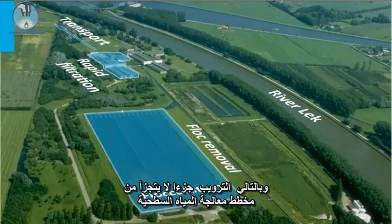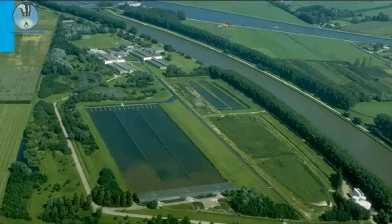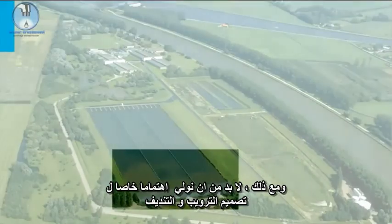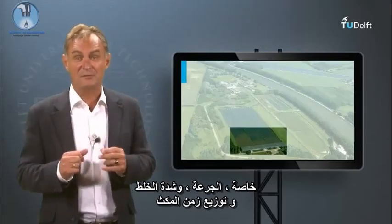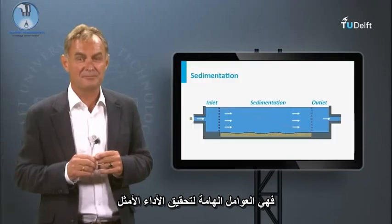Coagulation is thus an integral part of the surface water treatment train. It is directly linked to the sedimentation and filtration process, making them more efficient. In the photograph, the formed flocs are clearly visible. However, special attention must be given to the design of coagulation and flocculation. Especially the dosage, the mixing intensity and the residence time distribution are important parameters for optimal performance.